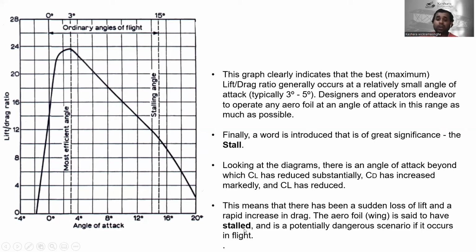If the aircraft is stalled, there must be a sudden decrease of lift, and there must be a rapid increase in drag, right? So the aerofoil wing is said to have stalled, and this is a potentially dangerous scenario if it occurs in flight. In flight, this scenario will occur. It is very dangerous. All right.